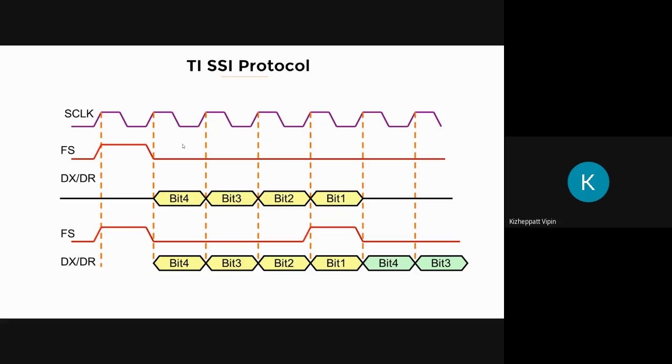What do you think? Next positive edge, sir? Is it the next positive edge? So he placed it here. If the slave samples it here, yeah, he may get it, but I mentioned, right, it is better to keep the sampling point at the middle of the data so that setup time, hold time, everything is satisfied. So maybe it's better to sample here on the negative edge. Okay, so this is one case where a single data, single frame transmission happens.